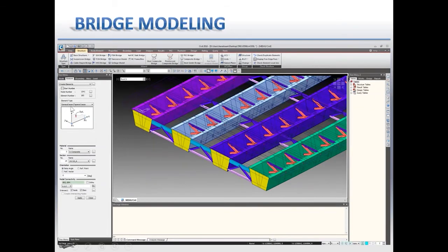So here under element type, you can click down and select truss. Because if you create it as a general beam, you're going to have to assign each individual cross-frame beam end releases, which also get assigned based on the direction of the element. This can be pretty intricate, and the easier approach is to just model them as truss sections.